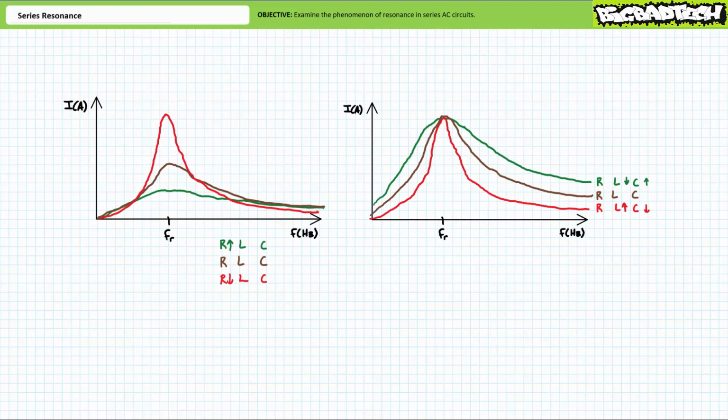Like I said, the significance of quality factor is a little difficult to conceptualize at first, but I'm hoping these graphs and the previous exercises illustrated how quality factor conveys a measurable indication of how selective a circuit is or is not, and how component level values not only specify when resonance occurs, but also the performance at conditions of resonance and at conditions of other than resonance.